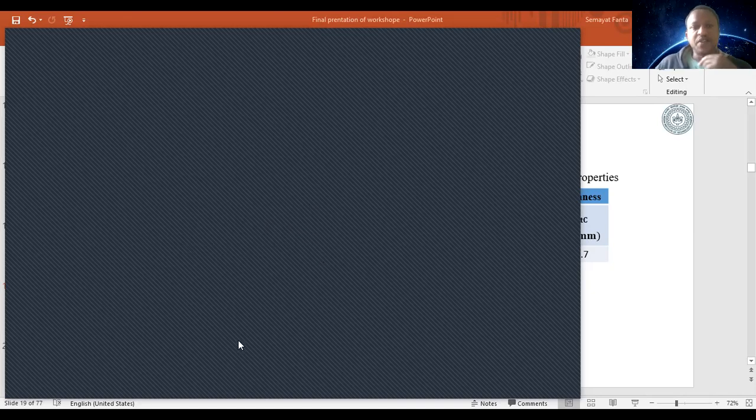Clearly, I will define them, and then let's go to the fracture energy, the interface fracture energy, that is the critical energy release rate, GC1, GC2, GC3. So GC1, let it be 0.21 E3. This one is 2.1 E3, 2.1 E3. Okay. So these are the interface properties.